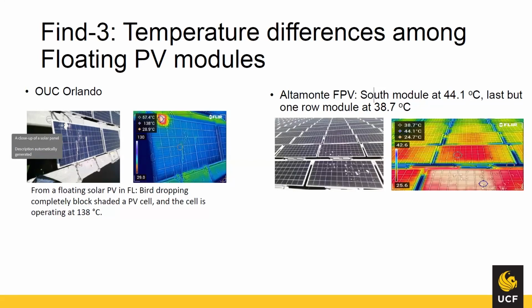Yes, I agree. But the cell is not what's getting hot, right? If you look at the IR image, the cell itself is not what's radiating the heat. It's the actual bird dropping. The cell is actually larger than the bird dropping and still showing blue around the edges. We might see that cells heat up all the time, and they're pretty specific about heating up. And it may be that the superimposed image itself is a little bit in error there, but there is a hotspot there.